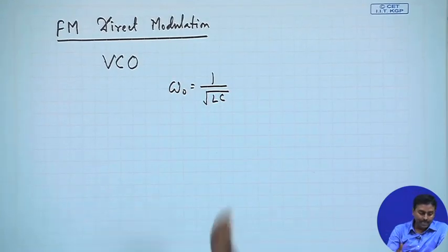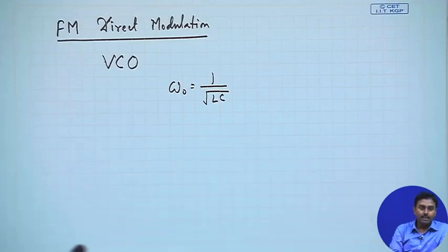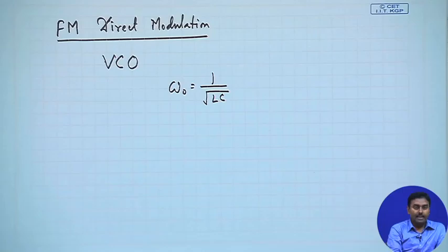What people have realized over the years is that if you have a semiconductor device and you reverse bias it, it acts as a capacitor. People have also seen that you can actually control that capacitor with respect to the input bias voltage. So, that was the initiative which started giving some hope to generate a voltage controlled oscillator.